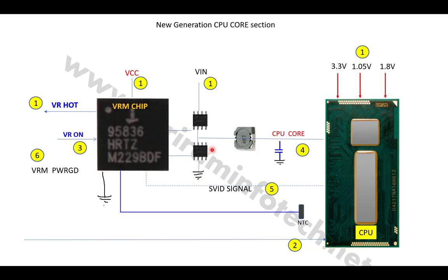It's called the nm. But in the newer generation laptop motherboards and their CPUs, the MOSFET size is very small, somewhere around 10 nanometers, called 10 nm. The TDP is very low. That is why the CPU core current is very low, because in older models the CPU required something around 30 ampere, but these newer generation CPUs require hardly 10 to 15 amperes. So for that, only a single chip buck converter is used. There is no need for multiple buck converters.